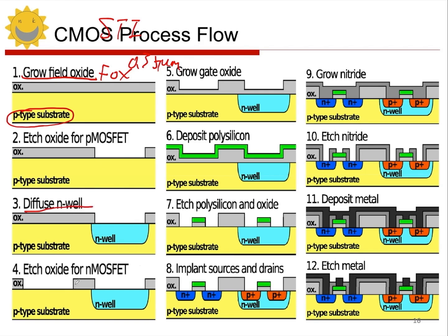For STI, areas with field oxide are isolated by STI before growing gate oxide for the MOSFET gates, followed by polysilicon layer etching using photolithography, requiring a mask plate. Next comes ion implantation, forming NMOS at this position, while P-type implants form PMOS within an N-well, leading us towards interconnection creation through nitride growth, then hole etching followed by metal deposition and its subsequent etch creating interconnect lines. Let's examine the three-dimensional chip processing structure illustrating CMOS process flows, defining mask roles during integrated circuit processing, introducing concepts like clear tone and dark tone explained next.